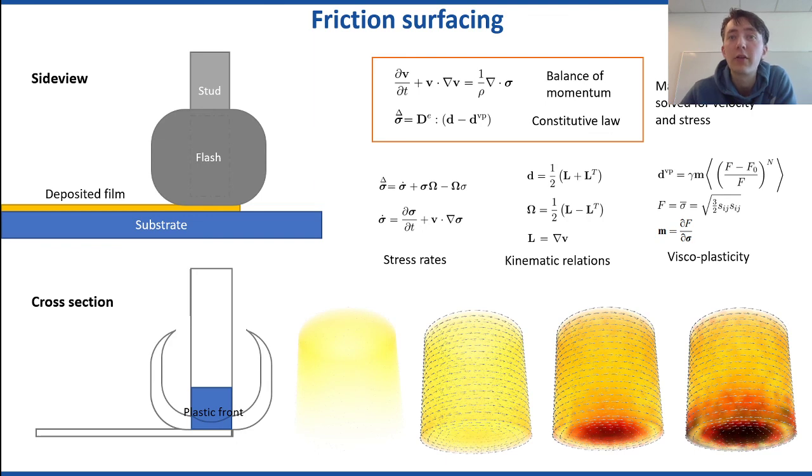The color here is indicative of the total amount of stress, in the product of the stress tensor with itself. And the arrows indicate the velocity. Now, I think I scaled the arrows with a factor of 1,000, so the arrows should be 1,000 times larger with respect to the geometry here. Again, this is spinning at a very high rate.